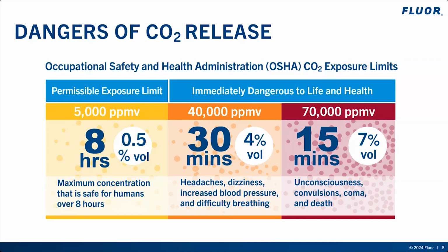OSHA has some CO2 exposure limits. There's the PEL, or permissible exposure limit, which is 5,000 ppmv, or 0.5 volume percent after 8 hours, which is the maximum concentration over 8 hours that is safe for humans.